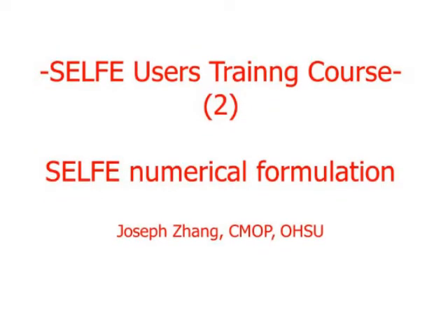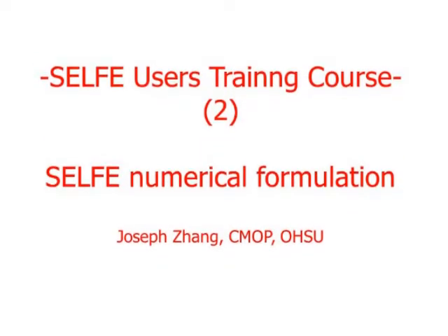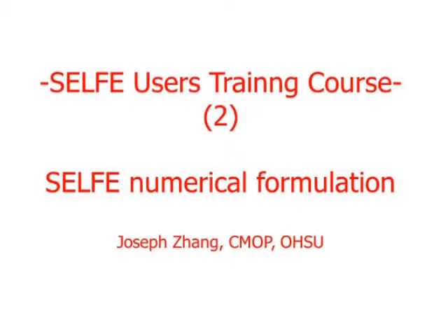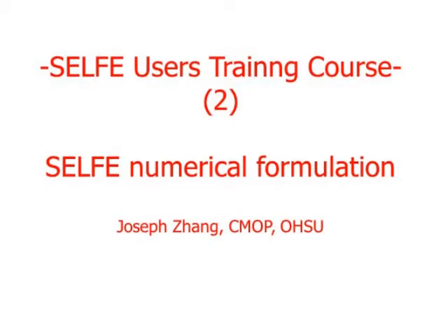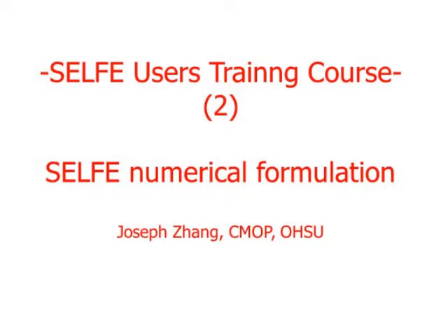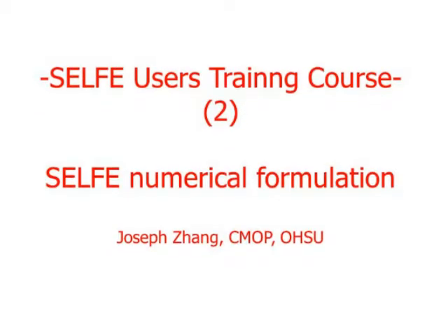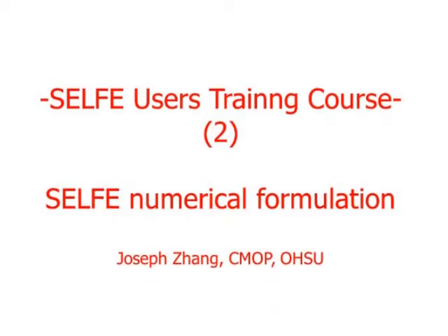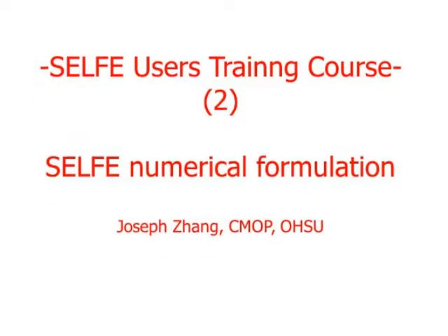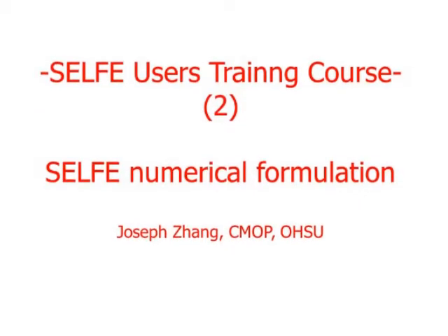And these are not going to be equally spaced, right? No, they can be anything. At 1, 2, and 3, 4, in an unstructured grid setting, the angle may not be 90 degrees. It can be any arbitrary angle, but they cannot be parallel to each other. So that's why this equation system always has a solution. It's well conditioned.